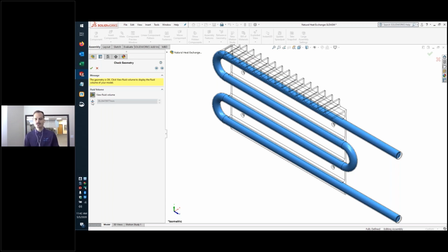In this example, I've really just got this copper tube that's the same diameter everywhere, so I probably don't need to worry about this option too much. If that copper tube is, let's say, 30 millimeters, I would just plug that in and that should be good to go. But if I had something like one of those fins or the bolt hole there that I was trying to simulate and make sure I've got air passing through it, then of course I might need to use a smaller number, 3 millimeters or something. That will make sure you've got a little bit more accuracy in those areas. Of course, that means there are going to be more cells in the mesh, more math to compute, as Sylvia mentioned. So it'll take a little bit longer, but hopefully it'll be more accurate.